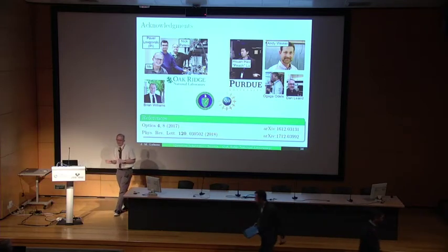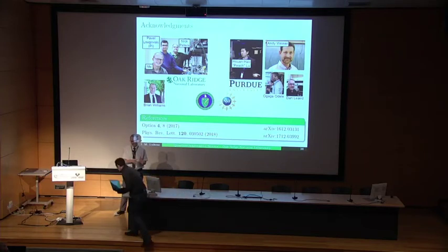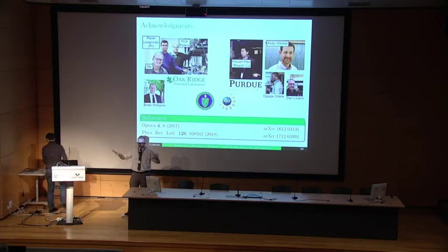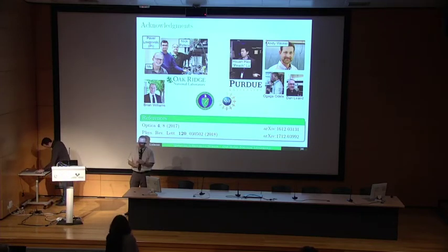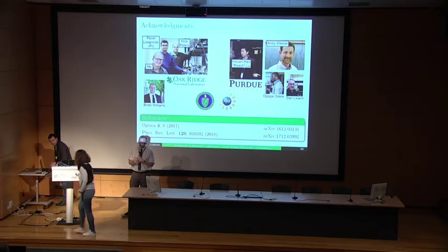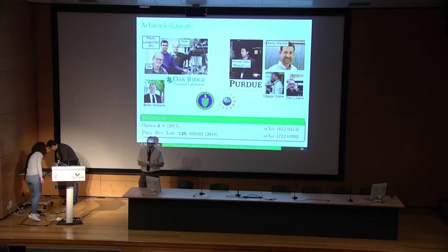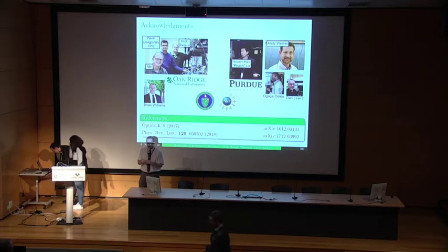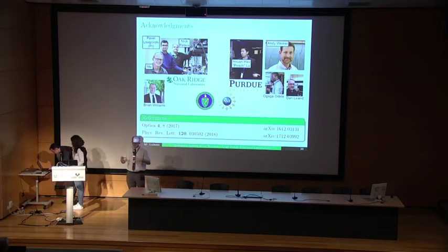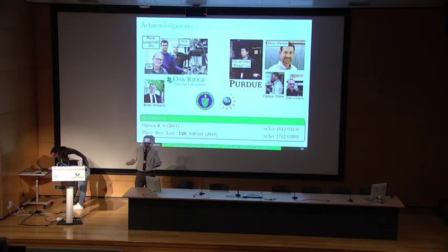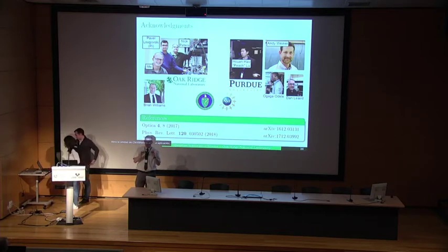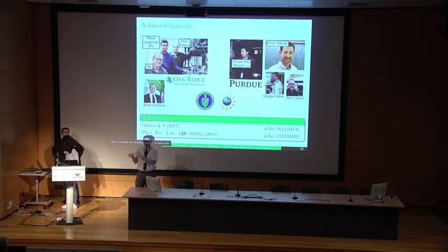Yes, so we do make a distinction between the intrinsic success probability, which is effectively the chance that our photon gets scattered into different frequency modes, and the insertion loss. The reason we make that distinction is because the insertion loss is a technical feature, for example of our fiber waveguide interfaces, where we have lots of loss, whereas the success probability is actually a function of the types of waveforms that you modulate. If we had no loss in our system, this would be how well the gate would perform in just unitary evolution. But we also have this huge technical problem of loss, and we want to characterize both so you understand the contributions to each. So the success probability is just the unitary scattering, and that's how we make the distinction.